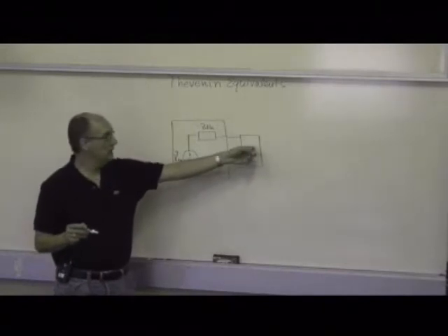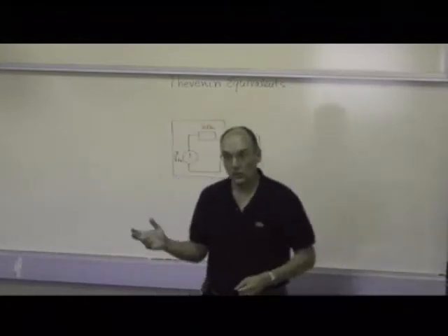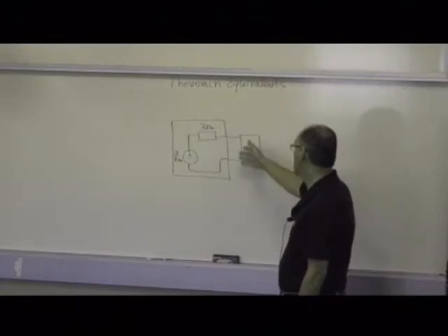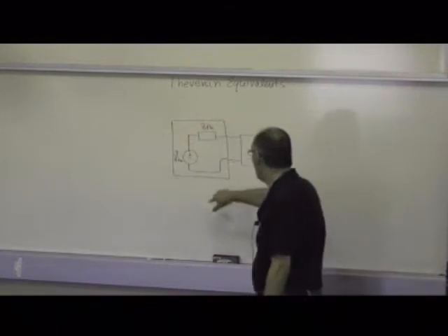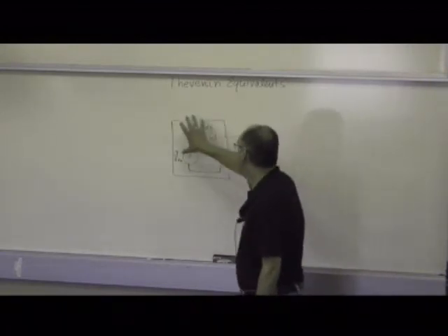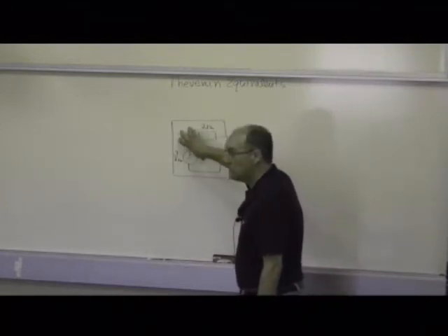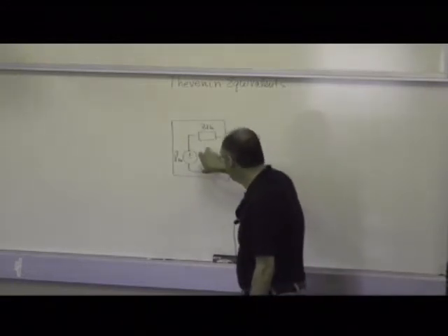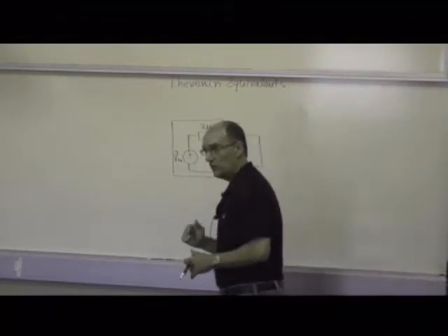This is also interesting if the smaller part of your circuit changes over time, which happens in power systems because demand varies, so you think of that as something that fluctuates periodically. So instead of having to solve the whole thing every single time this changes, you just solve a simplified circuit, because this could be, for all you know, the entire US west of Massachusetts. That's a huge circuit. When you simplify it to something like this, you really have a much more manageable problem. That's why we do Thevenin equivalents.